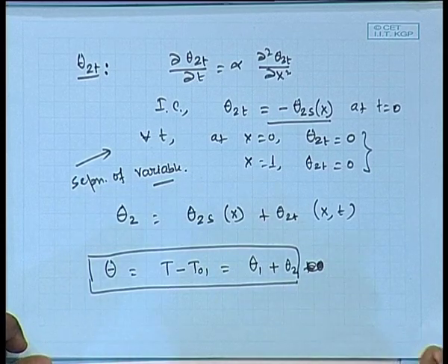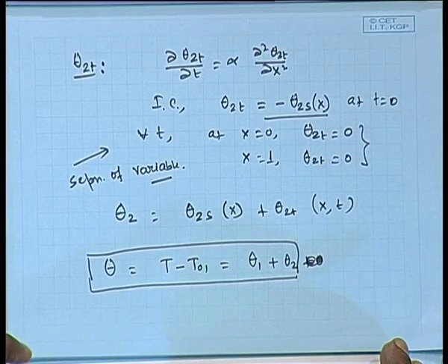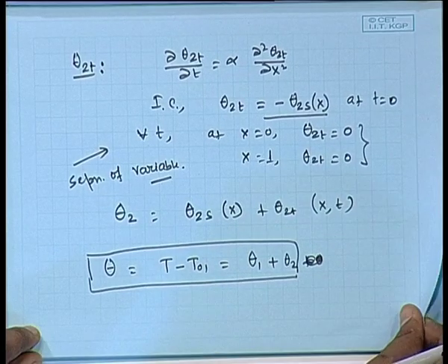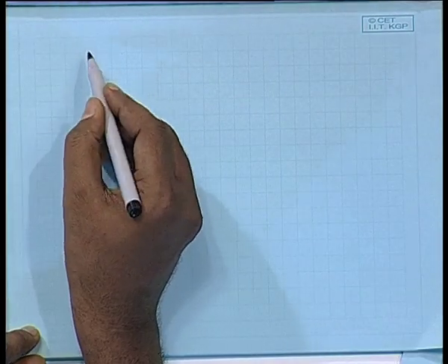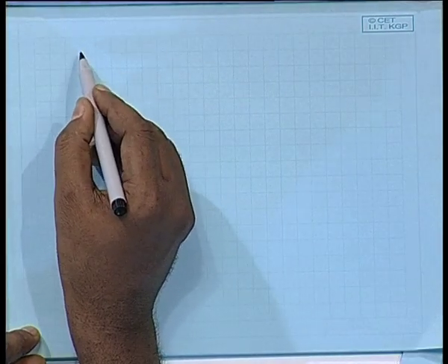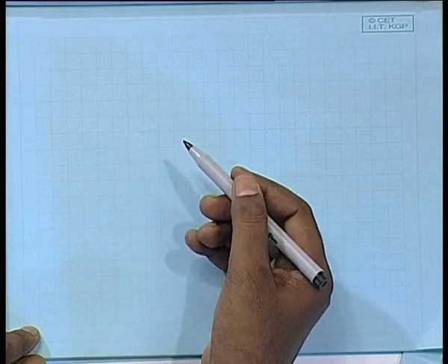Now, we will be showing some of the actual problems in transient heat conduction using separation of variables. We will be taking up all possible boundary conditions: Dirichlet boundary condition, that means a constant temperature condition; one boundary where, let us say, a constant heat flux is coming in, or it is insulated, that means the derivative of temperature is 0 at that boundary; and a boundary open to atmosphere, that is a mixed boundary condition, conduction plus convection.